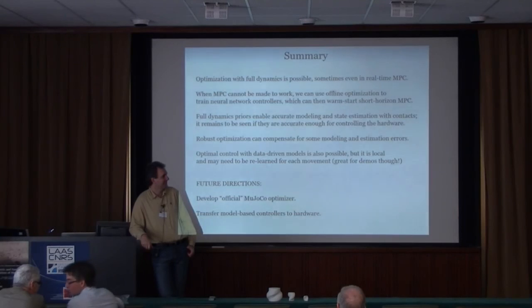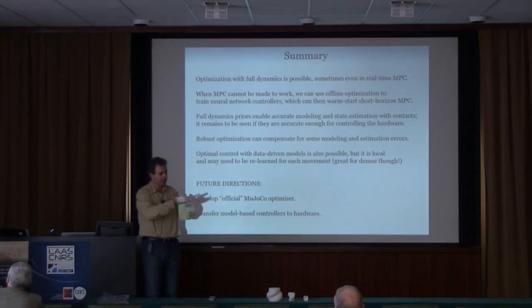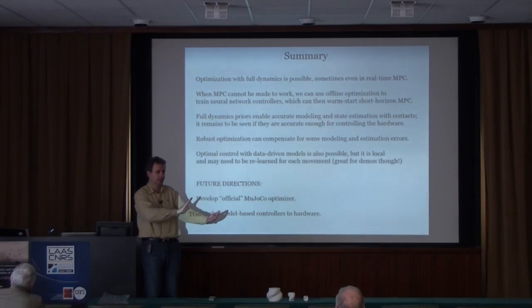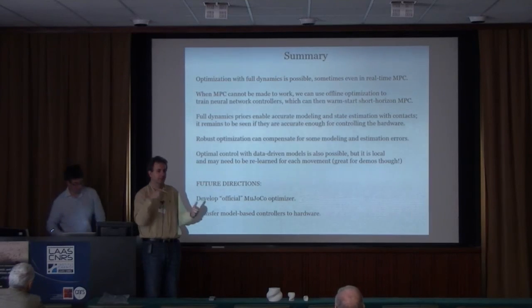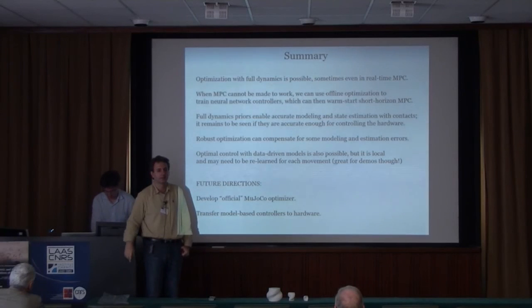I haven't specifically analyzed what that does to passivity, but we have a friction constraint, so you can never pull on a contact, you can only push. I think that already gives you passivity right there. You're going to get a force opposite to velocity, so you're going to get negative energy injected by the contact.